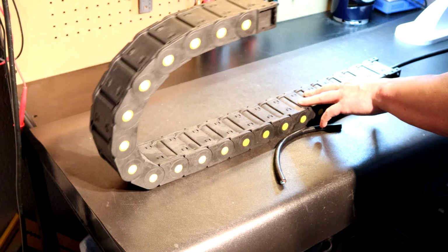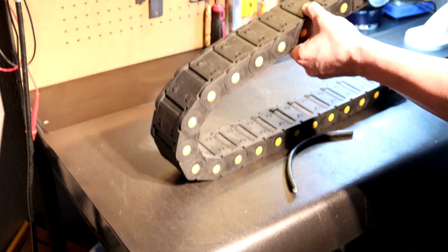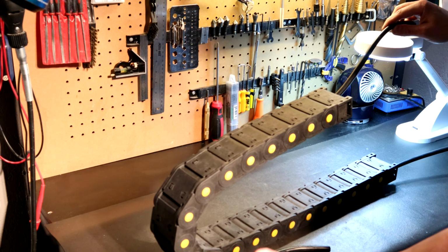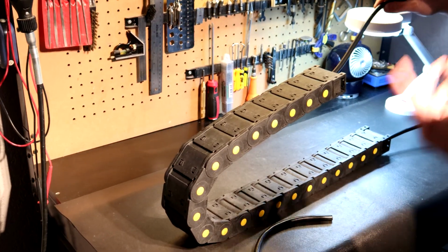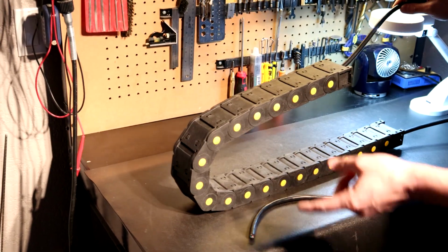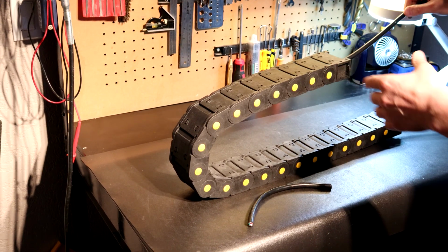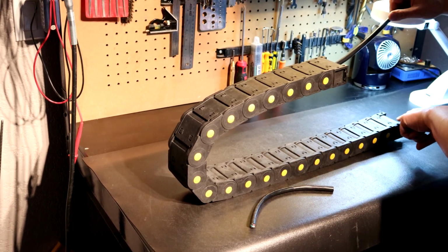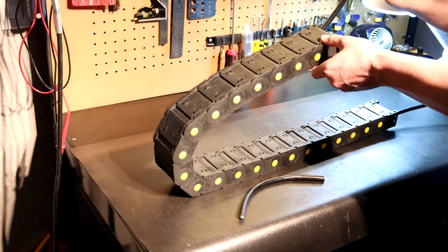Depending upon how long your axis is on your Y, that's how you're going to dictate your motion, and that should also be how you dictate the length of cable. I've told many guys that want to measure for the proper length cable, take a string, run it through your cable chain, and it'll simulate a cable. Now, is it going to simulate the way the cable moves? No, it's not. It will give you a general length. To get an accurate length, I recommend increasing it by at least 20%. That gives you a buffer, because once you run this cable through the chain, you're going to lose actual length in your cable.